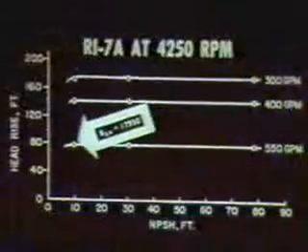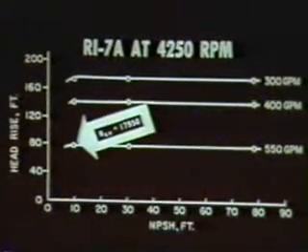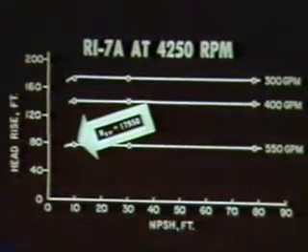Cavitation now extends along the suction surface to the hub. Note the vortex at the tip of the leading edge. Here, the tip vortex extends into the vane channel. Also note the formation of tip vortices in the rear channel.